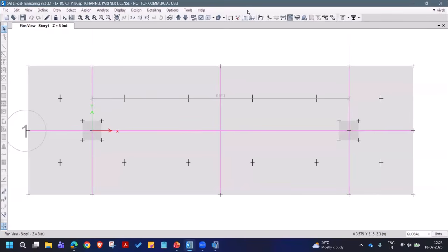If the forces or the stresses are sensitive in certain locations, mesh size will affect the design and other responses. Yes, that is expected, but you can make the average instead of getting into the element level details. Use the design strips, that should give you a reasonable output always, because handling the finite element output will be a cumbersome process.